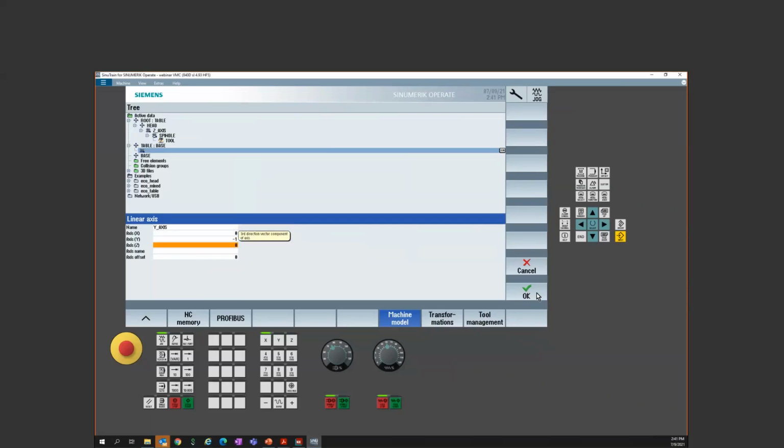And this would be the time where I would ask the class, anybody know why we would use a -1? And the reason being is, if it's +1, I'm describing tool motion, right? When we program, we always describe tool motion, right? So if I want to take that tool to the negative direction, I tell it negative. If my y-axis was up on my spindle, I would be moving negative.